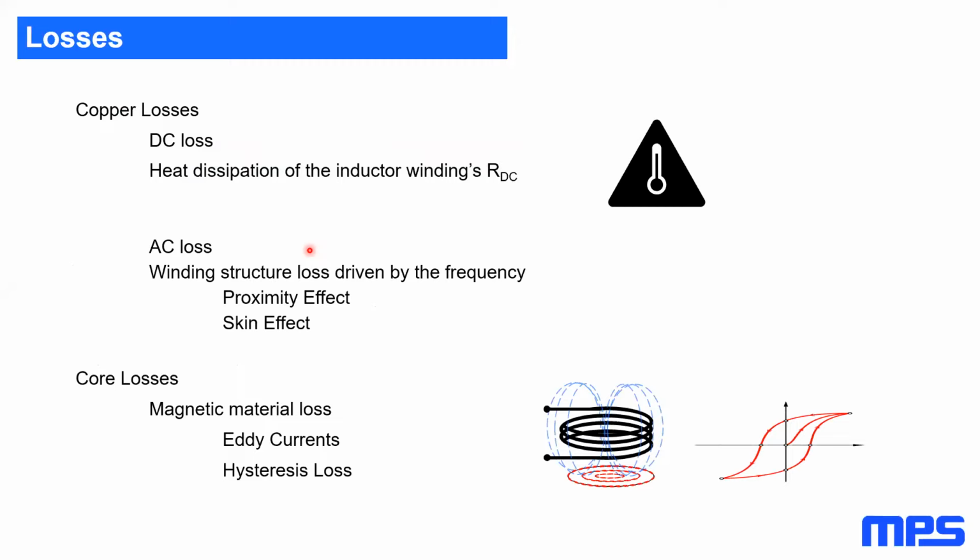When measuring the complete losses for inductors, you need to pay attention when you have several alternatives. At first instance, from the datasheet, they may look very similar. Maybe it's the same size, same RDC value, very similar currents, but at the end, when measuring and comparing efficiency, there may be some differences. And this is regarding the whole component, so the copper losses and the core losses.